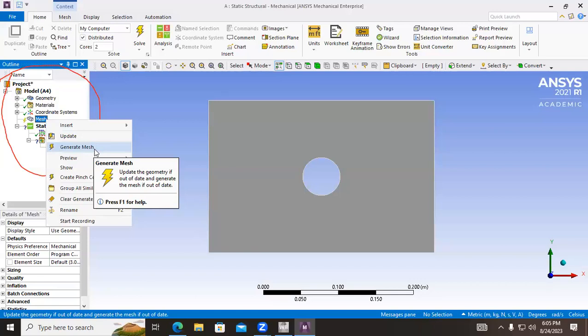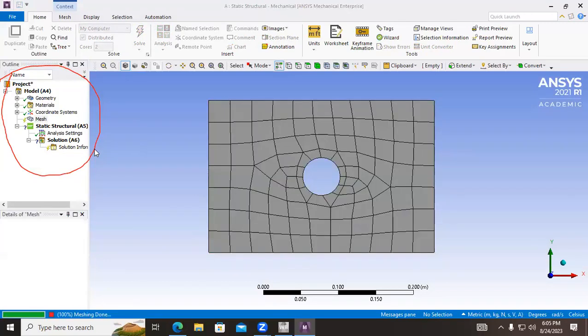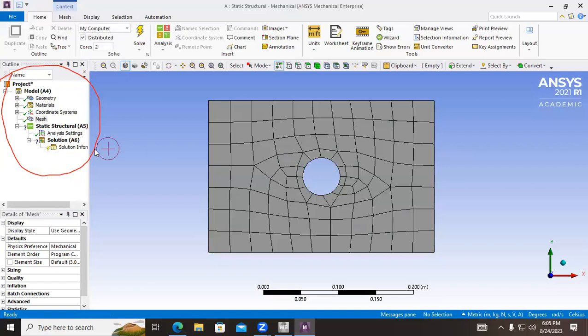We're using just the default settings to generate our mesh. So default size, default shape. It should be pretty fast because this is not a very good mesh, but it'll serve to get a point across. Okay. So was everyone able to generate a mesh? It maybe doesn't look exactly like this, but it looks something like this.